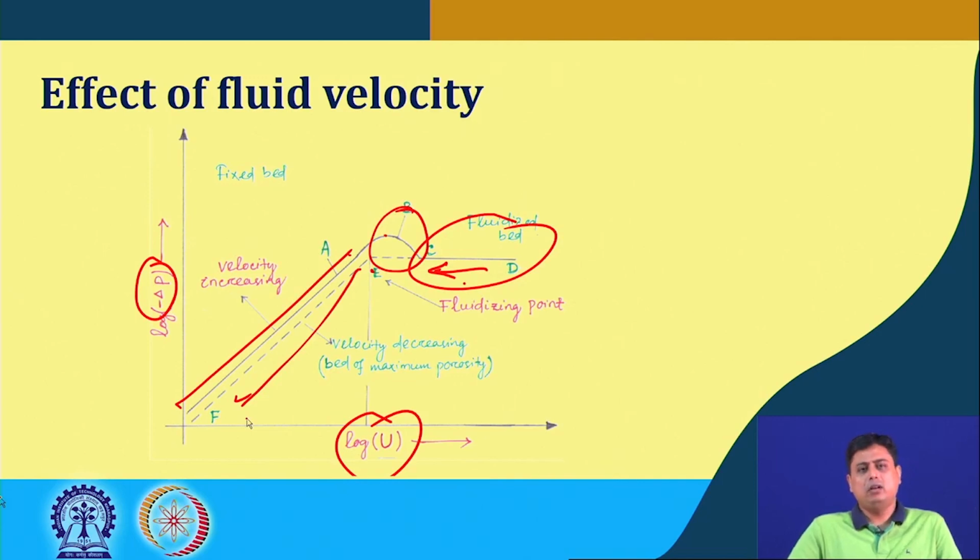So when we have the highest voidage possible, from there if we decrease the superficial velocity, it would follow the same linear path but not an identical path as while increasing the velocity. There are several studies which find expressions relating the startup and shutdown procedures, that is, the startup operation and its closing down or the deaeration process.